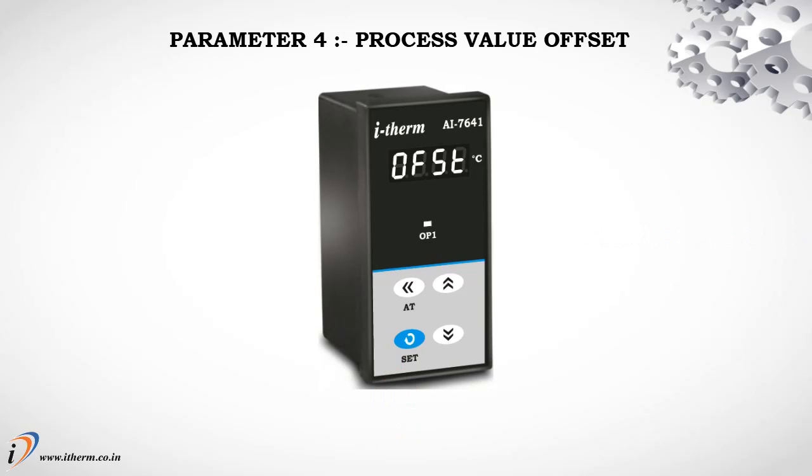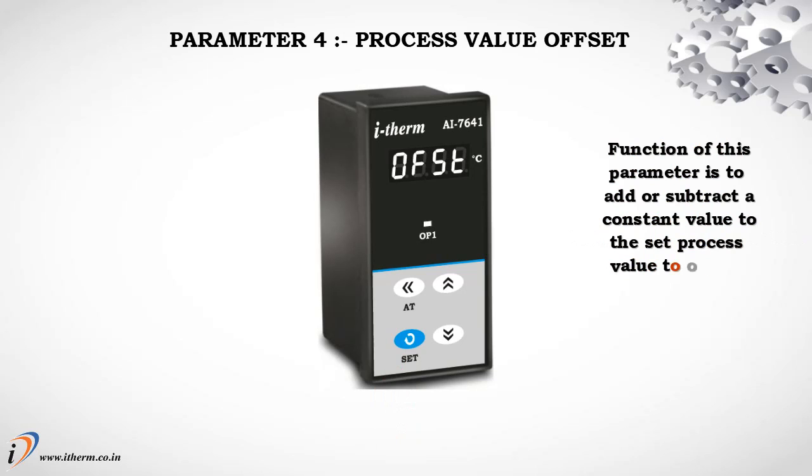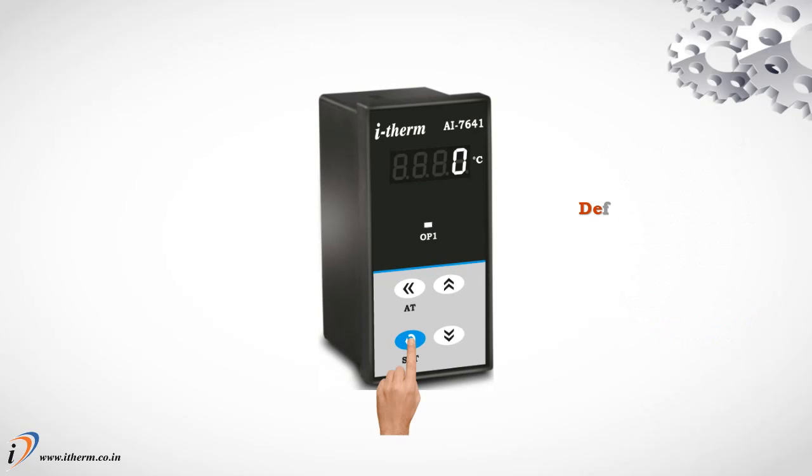Parameter 4, process value offset. The function of this parameter is to add or subtract a constant value to the set process value to obtain the final process value for control application. Default process offset value is 0.